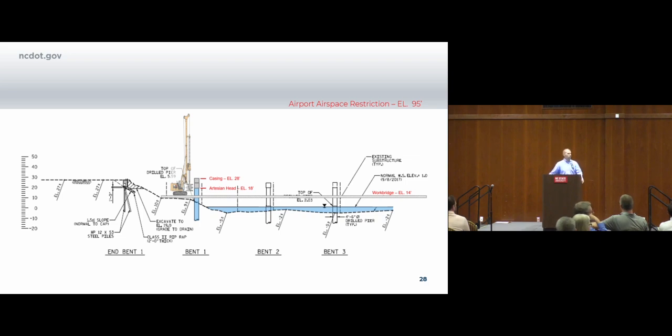So we ended up having to switch to pipe piles. So we had to redesign. Contractor's got all his casings in the ground, all his cages tied for his drill shaft. Work bridge designed for a certain elevation and everything, and had to switch to 30-inch pipe piles, went around with that, got the redesign. So now we have to basically get rid of all the reinforcing steel, pull the casings, order all the new pipe piles, and basically a huge renegotiation of all the original work. We're shut down for 3-4 months because they can't do anything until the moratorium's over. So huge project impact, right, because of this artesian.